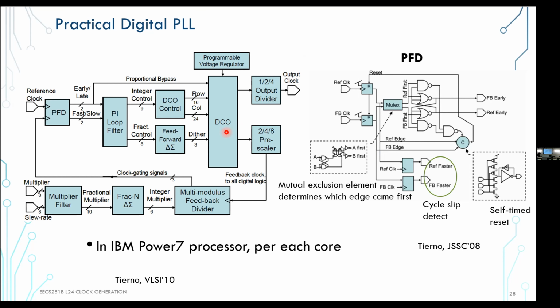In a lot of these digital PLLs, you're going to see sigma deltas all over the place because they bank on the fact that there's some low pass filtering happening inside, either the VCO or the loop overall. And basically, this shapes out that quantization noise. A similar trick is here on the fractional and delta sigma in the divider loop, right? So far, we've only looked at dividers that are integer. Remember, DVFS, you want to have continuous frequency scaling, for example, right? So how do you achieve that? You can't scale the ref clock, it's fixed. So you need to have a flexible divide ratio.